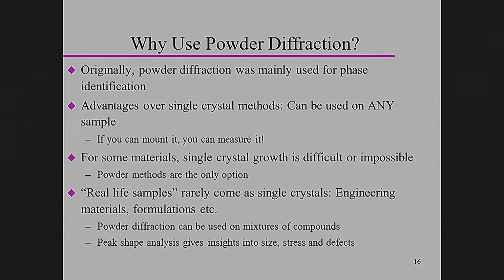So if you want to analyze them, powder diffraction is the method of choice because you can use it on mixtures, okay? Another really cool thing about powder diffraction is that you can analyze the peak shapes, and that can tell you something about particle sizes, stress, defects, all of these things that engineers really pay a lot of attention to because that is what determines the performance of the materials.